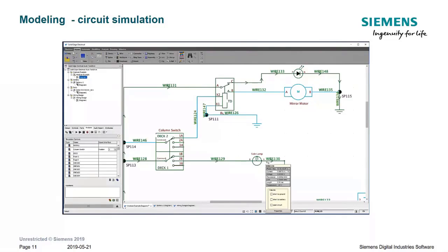So if you have, as Chad alluded to, if you are concerned about voltage drop, if you think that you may have wrong-sized the fuses or the wires, you can inspect the design, see what current is being drawn at various places. Now, notice that all of this simulation is being done without a prototype being built. A physical prototype is not necessary.